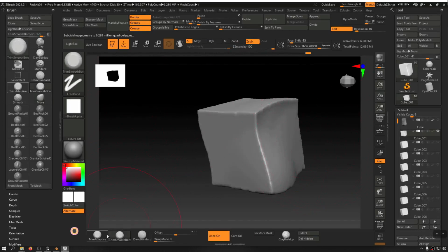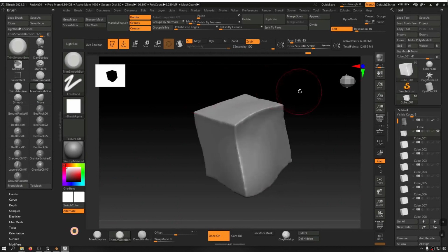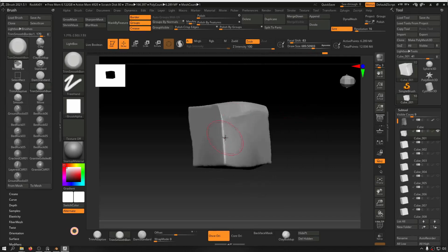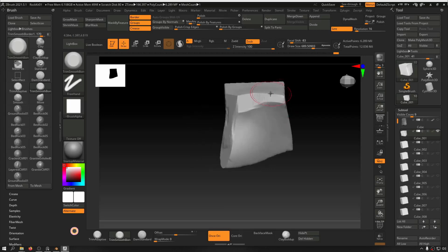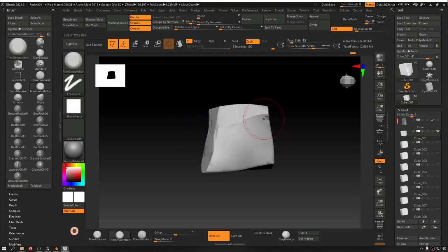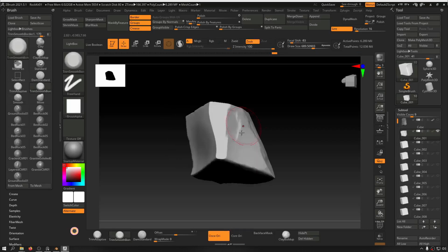And now it's time to start to do the trim smooth border to introduce the planar changes, and then we apply the noises as well. So let's try to hit these edges, and every time you feel that it's a bit too noisy, you can hit Shift and smooth the result as well. Just try to smooth it out a bit so that when you later on introduce some alphas, you really do not get a lot of edge noises. So just make the edges a bit smoother than the rest.